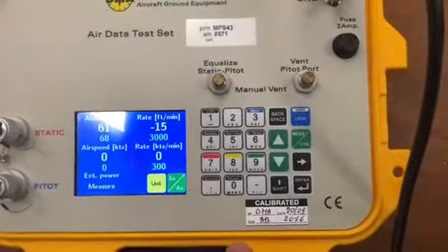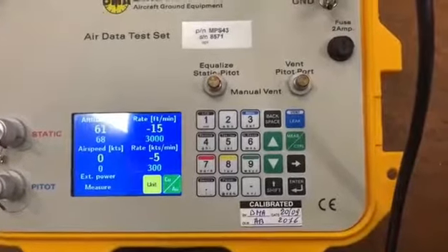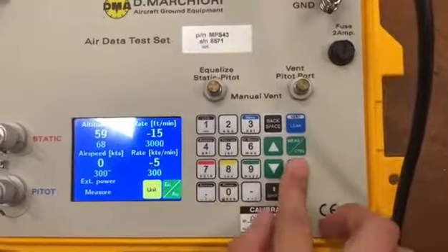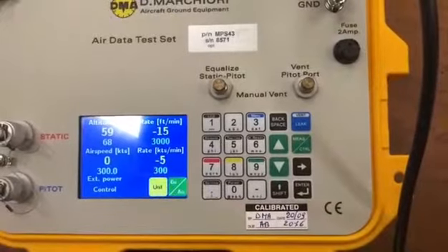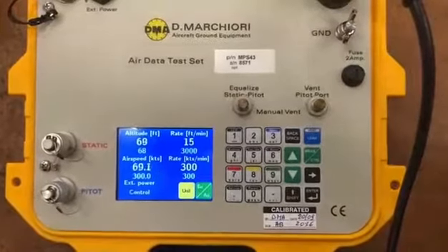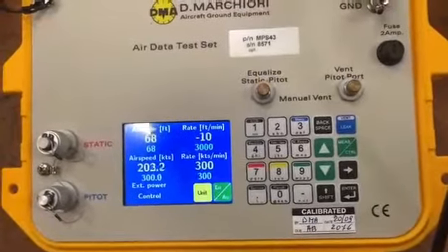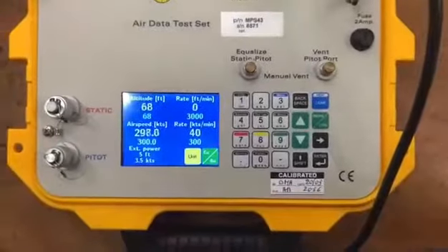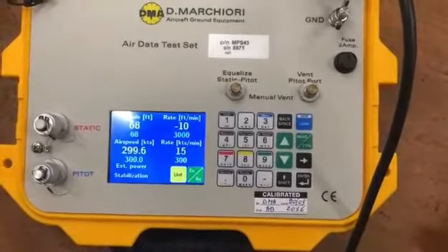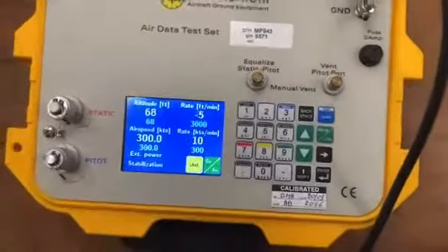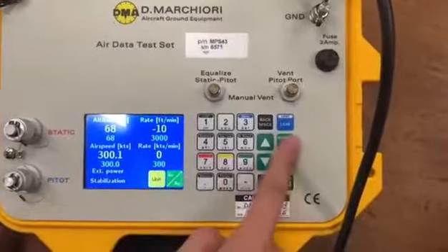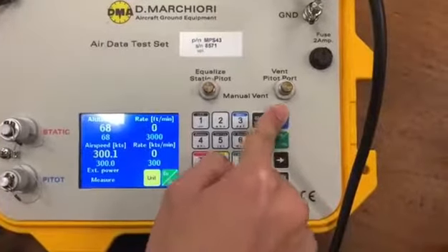We are doing our first simulation by setting the target SP to 300 knots to simulate pressure and showcasing the control mode. So simply select SP, type in 300 and enter, and set it to control mode. Now the simulation will run. Okay, now that airspeed has reached 300 knots, we can set it to measure mode, and then we can do a leak test.